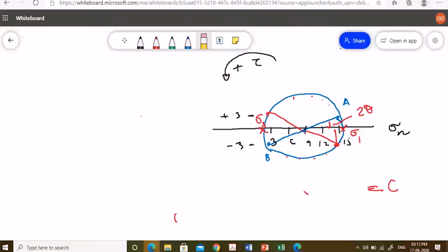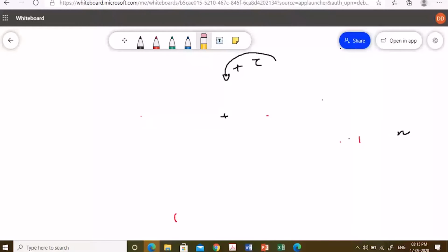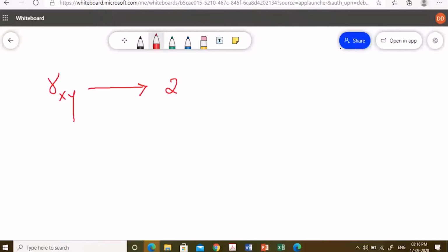Now I will go to a thing: if I can draw Mohr circle of stress, can I draw Mohr circle of strain? The answer is yes. We can also draw Mohr circle of strain. Only thing you have to remember when you are drawing Mohr circle of strain, everything is same. Only thing, just a minute. This gamma xy, when you are using this gamma xy, this will be replaced. Okay, this is coming from basically 2 tau xy.